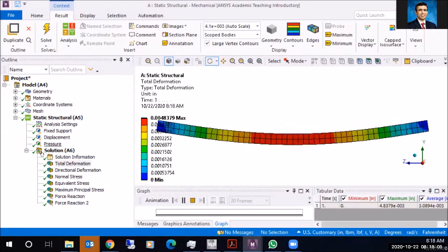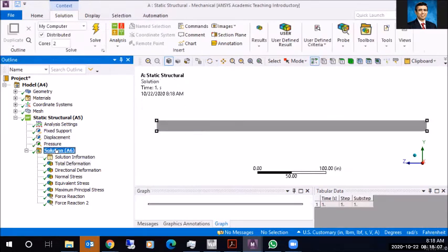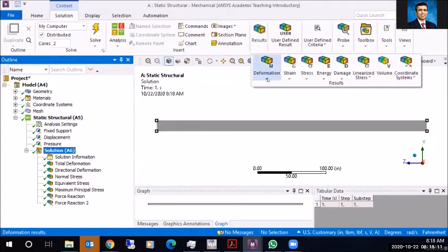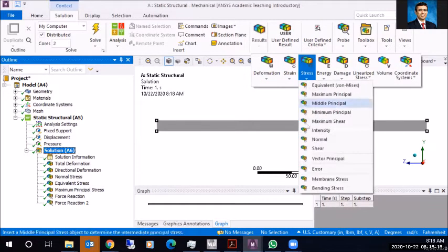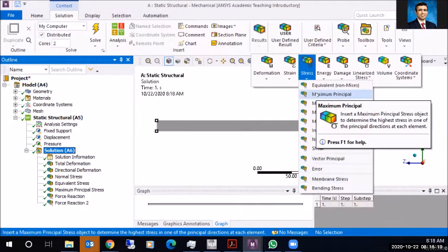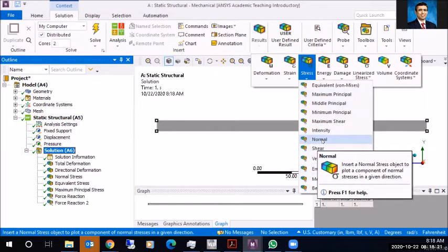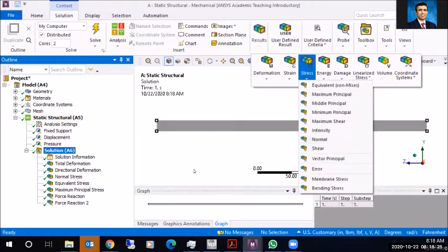And when we were looking at creating results, you go to results, and now because we are doing solids, your stress results are no longer grayed out, but you can select stress. And one of them is a normal stress. Normal is perpendicular to the face, which can be considered an axial if I pick the proper face.